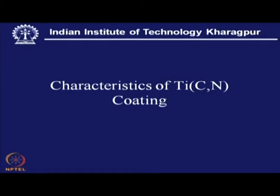Now, characteristics of TiCN coating, that is already known to us. That means this titanium carbonitride is more chemically stable than titanium carbide, while resistance to abrasion will be better than that of titanium nitride. So, this is something in between two extremities, that means titanium carbide and titanium nitride.